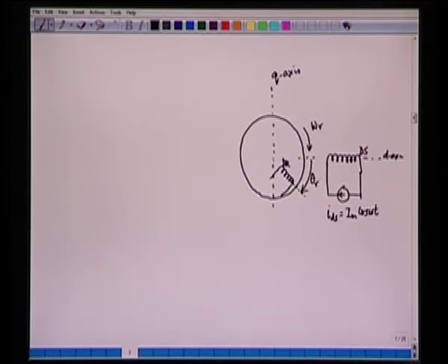Now if we want to find out the flux linkage in the d axis rotor or dr winding due to the stator current, which is Ids, that's equal to Im cos omega t, we can write down the flux linkage as follows. The flux linkage in the winding dr due to the stator current is given as Md Ids into cos of theta r, since the rotor has moved through an angle theta r. So this is the flux linkage with the winding dr, and the dr winding is now rotating at a speed of omega r.